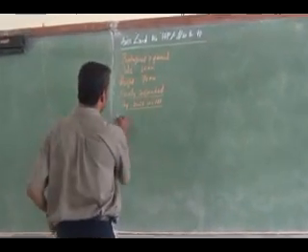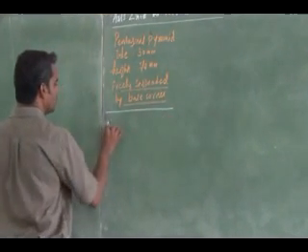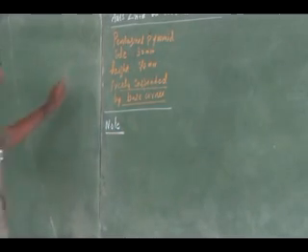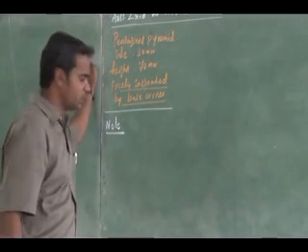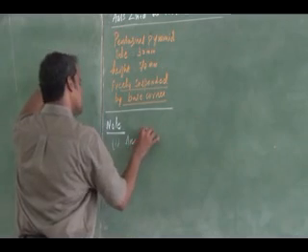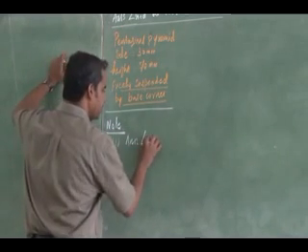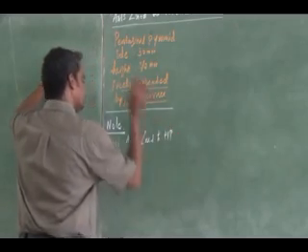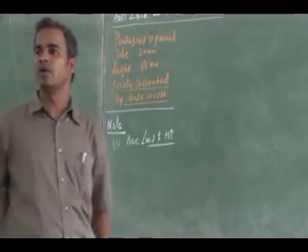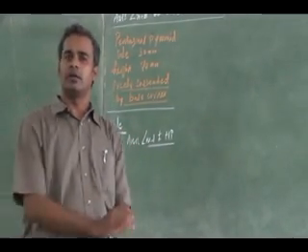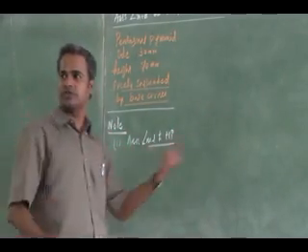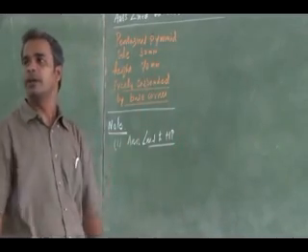So make a note for this problem. Axis inclined to HP problem. This is hidden data you have got: axis inclined to HP. So where do I have to draw the base of the pyramid? On HP. Axis inclined to HP means you have to draw the base on HP, that is below the reference line, and then proceed for the front view.